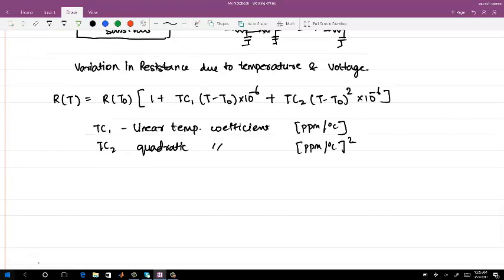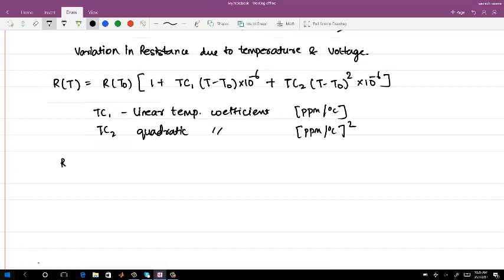So any design document will specify how much the resistance can vary depending on the temperature. So if you are making any design, you also take care of how much it varies. Another interesting thing is that though I am saying all the time that this is a passive resistance, it has a voltage dependence. And this voltage dependence, you can say, is because this is N-type silicon or P-type silicon, diffused or crystalline kind of silicon, where things will change depending on the voltages applied across the resistance. So it also has a voltage dependence across the, sorry,